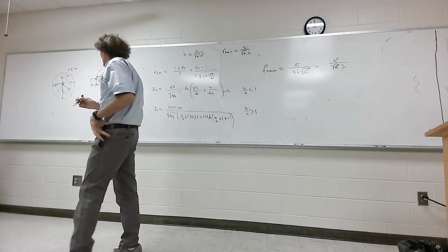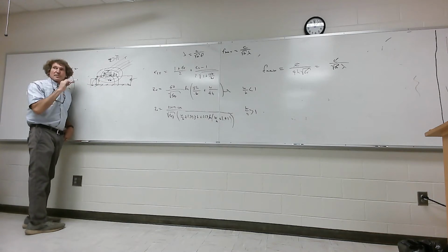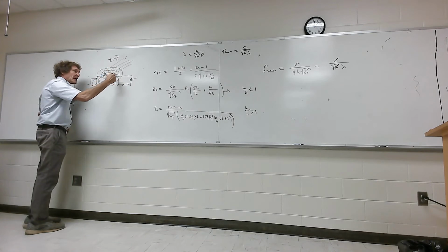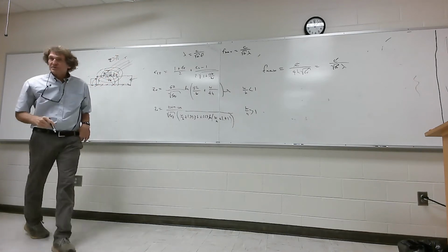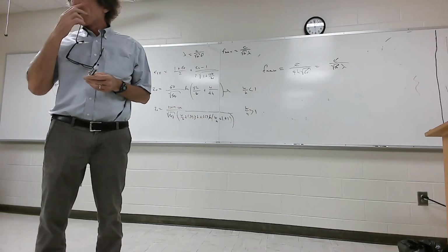Here's what actually happens in the dielectric there. Remember, that's copper on the back. That's copper here, all right? It'll be a very lossy waveguide. The energy is going to try to ricochet back, but it'll spray off into space. You'll lose a lot. So that's the maximum frequency of operation that you can get away with on these things.